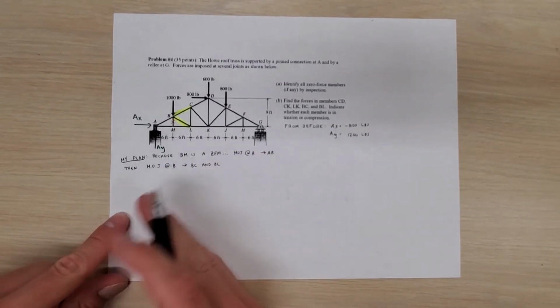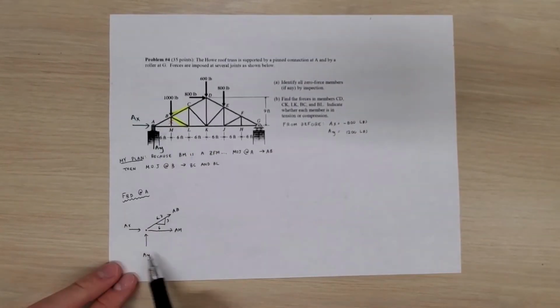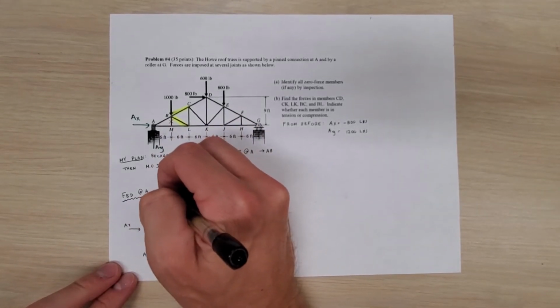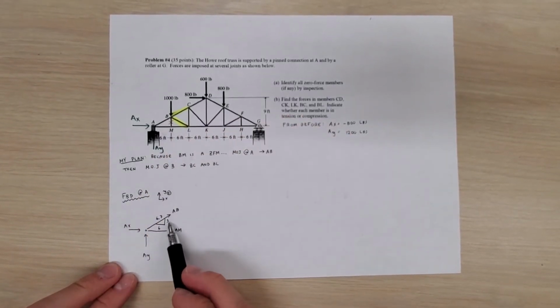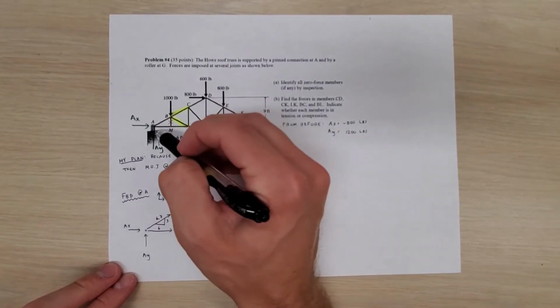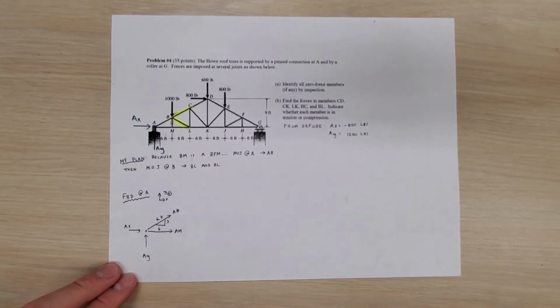So what I have to do then is draw a free body diagram of point A, and I'll do that right now. So here's my free body diagram. I'll include an XY axis just to be consistent. And what we can see is that AB is just like what we did before with CD. It's got a height of 3, it's got a width of 6. So we know that hypotenuse is 6.7. I use that for similar triangles.